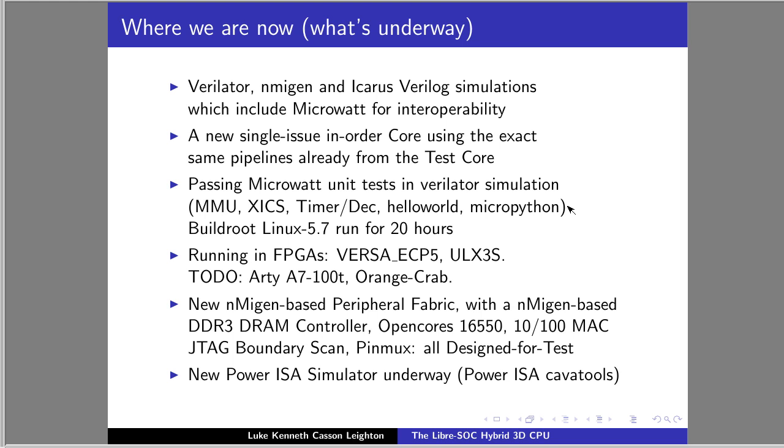The majority of open hardware development has been on FPGAs up until this point. And if you look at it, if you want to repurpose an FPGA's pins, so you want the pins that were previously used for I2C, you want to use them for a UART instead. Well, you just rebuild the bitstream for your FPGA and upload it and go.